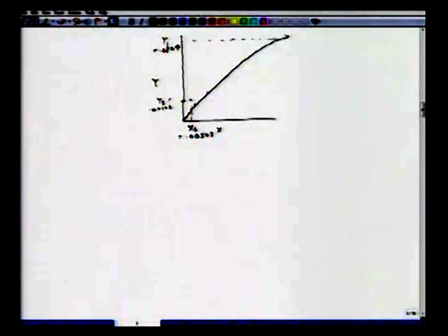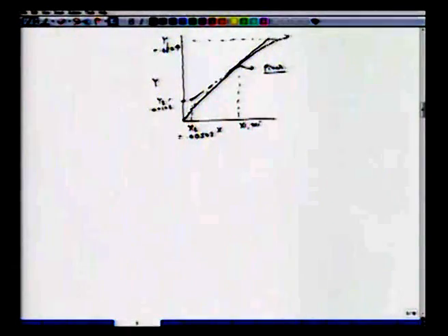So now once we have x2, y2, on the exercise which we did earlier, one has to be careful to find out this minimum amount of solvent. So you can see that there will be a tangent like this. So this makes a pinch here, and we have discussed in the previous lecture that this will give you x1 min, the maximum concentration of this spent solvent.